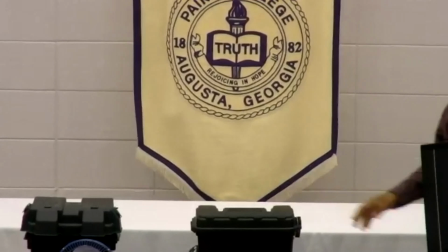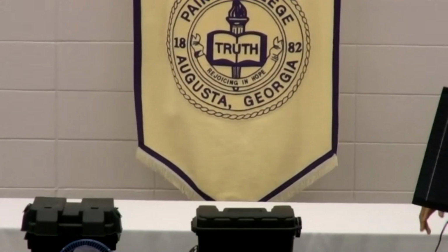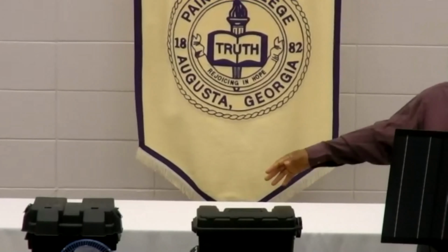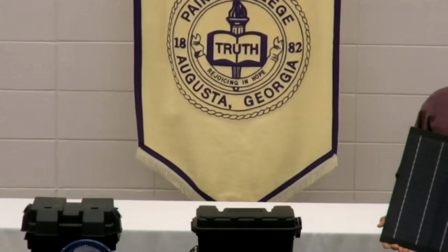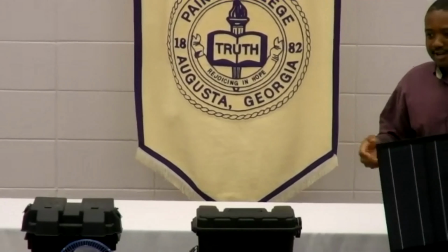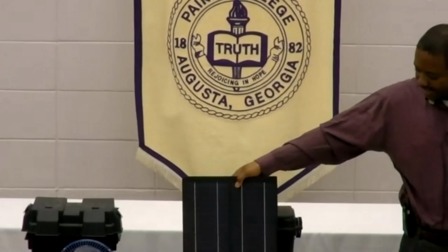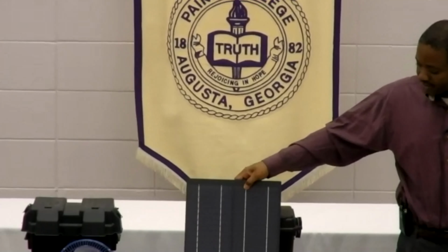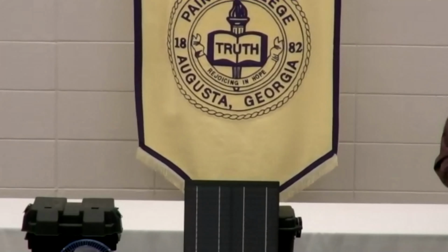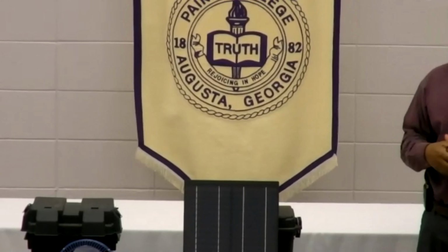So to answer your question, what are the key components necessary: we have the solar panel, you need the solar charge controller, and the battery. Now, the type of battery that is utilized is very important. So we reiterate with the students, you cannot use a regular battery that you use in your vehicle. It's usually a deep cycle battery. Examples of these are normally those found in golf carts. Those batteries can have a deep discharge without damaging the battery. So these are the type of batteries that we utilize in this case.